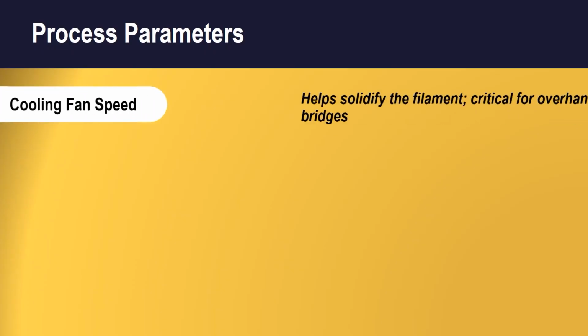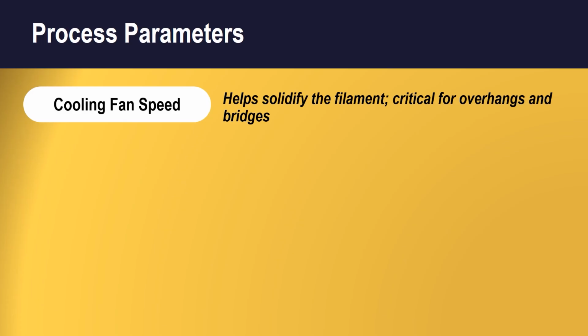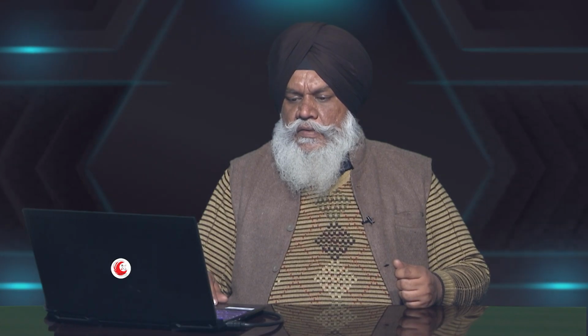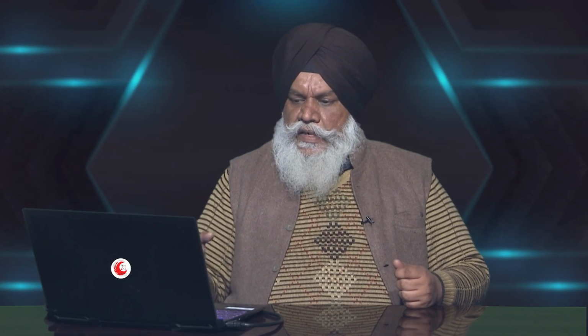In some of the commercial packages, they call it a solid structure. They call it a dense structure. So basically, I can express it in terms of the percentage of infill, basically adding the density part. Then cooling fan speed, this is again critical. If you put in a more dense part, it has to be high so that the heat is extracted.